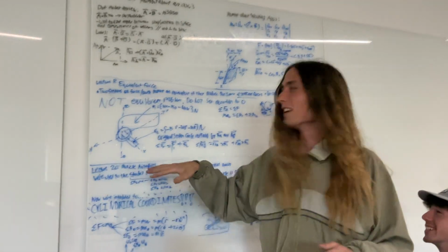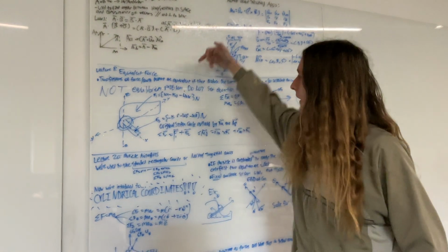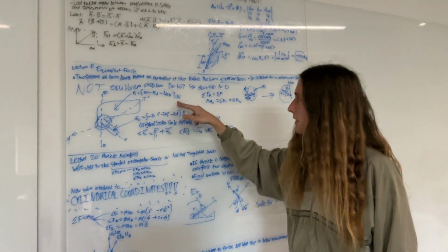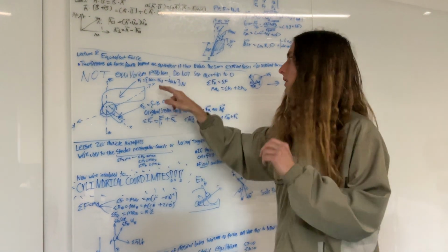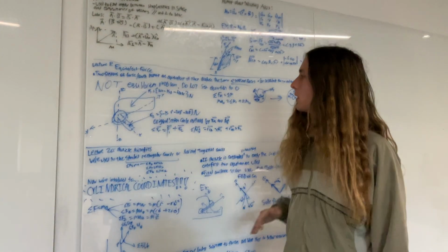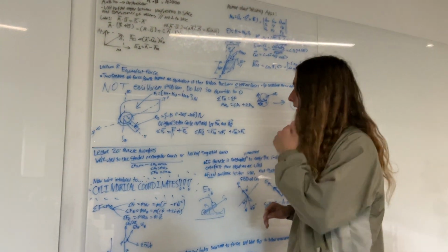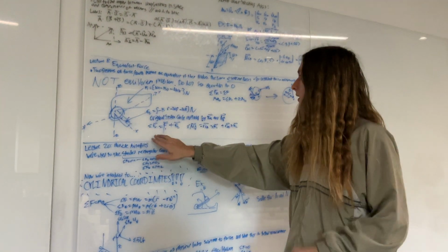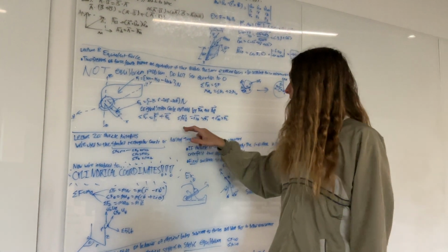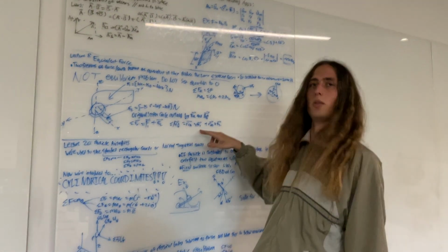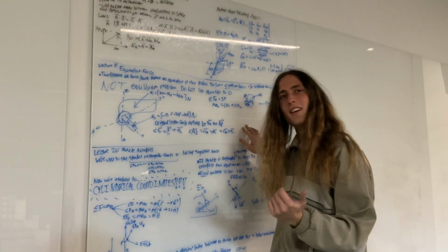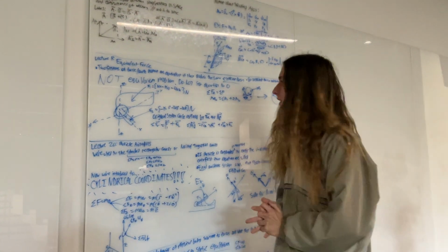So this is a grinder. We had a force being applied there. This is the components in the IJK format, and there's also a force here. And so we want to turn that into an equivalent force system. And really all it is, is summing the forces here, and then for the moment we did have to do R cross F, and then adding those two R cross Fs to get the net moment.